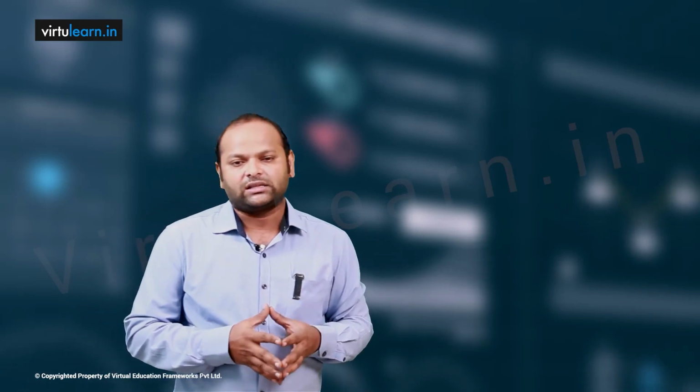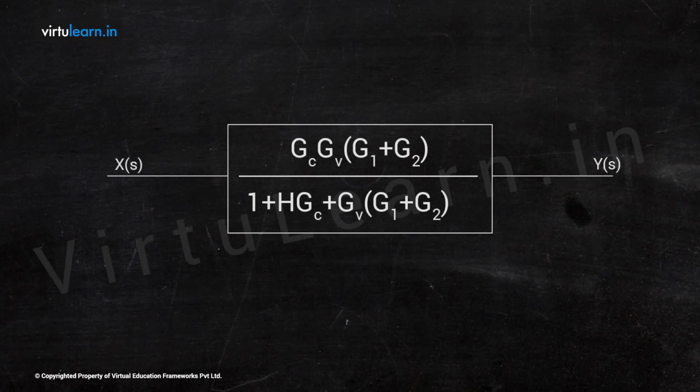Let us take another example. In this example, there are three processes G1, G2, G3, where using G1, G2 I have an internal loop, and after that G3 is cascaded, and before that we have a controller KC and a feedback transfer function H. I want to find the overall transfer function of this system, which is Y of S by X of S, using block diagram reduction technique.